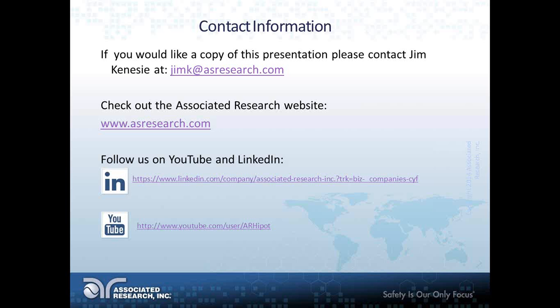Basically what Syed just asked was if people are performing both bonding and continuity tests in their testing environment. That's a really good question. I do know that there are customers of ours that do perform both, but not both on the production line. What they do is they'll perform their ground bonding testing for their prototyping phase, and then they're sampling on a sample basis. So maybe they'll pull a random product off the production line, take it to the lab, and bond test it. But as a routine test, they're doing the continuity testing. So in that sense, yes, they're doing both in-house, but through different aspects.